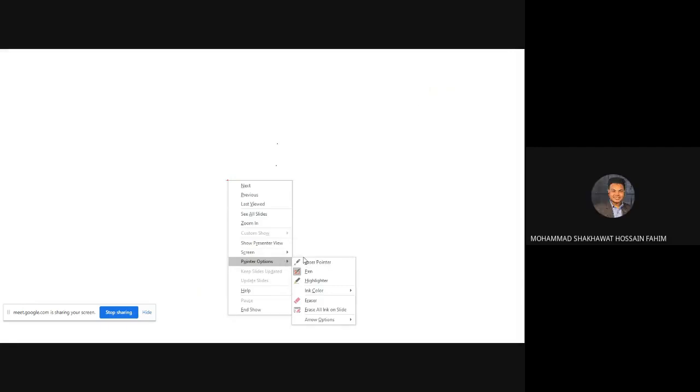And what are the merits? What are the merits for the common emitter amplifier? High voltage gain and high current gain. It has high voltage gain, high current gain, and very high power gain. So these are the merits of the common emitter amplifier.